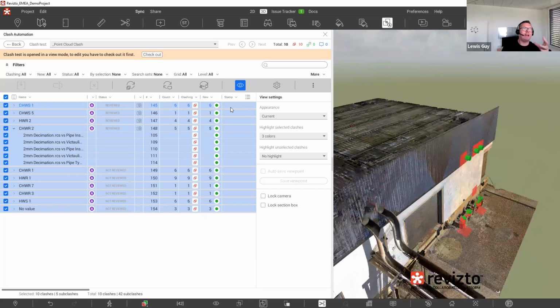And then in Revit, we also use the view range. So we use the top and bottom plane of the view range to connect what area of the 3D model vertically is then connected to that sheet. So any issue that you raise in the 3D model that sits within the view range of that drawing will show up on that drawing and be connected to it. With other tools, in MicroStation, you use the extents of the section box with the floor plan to do that. So that's how it's done.